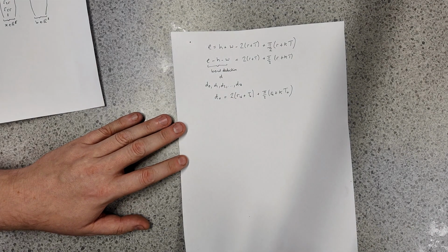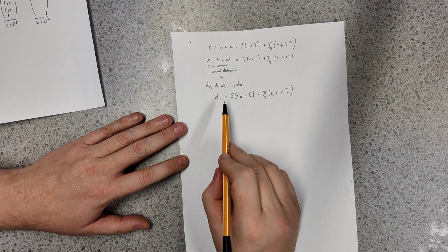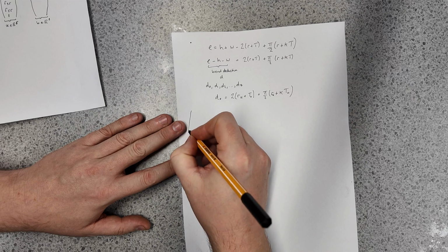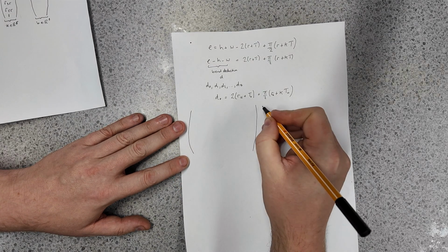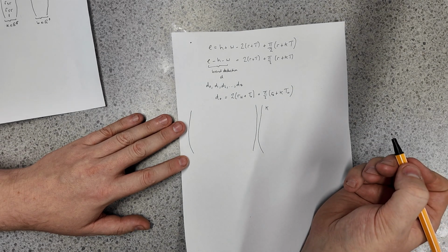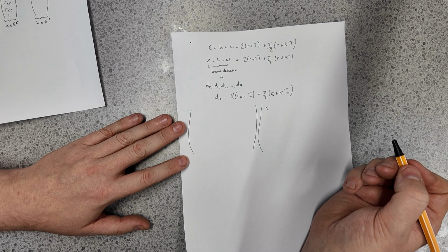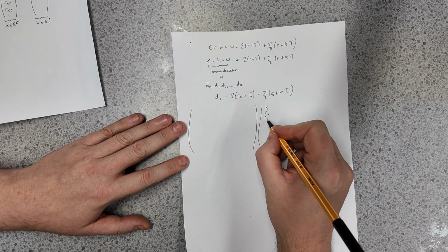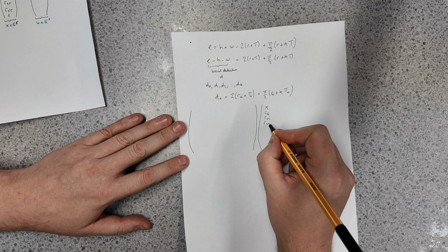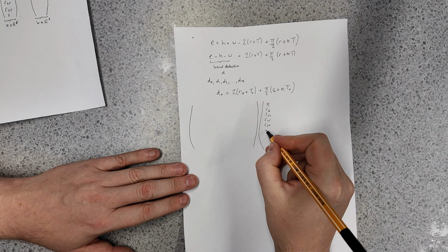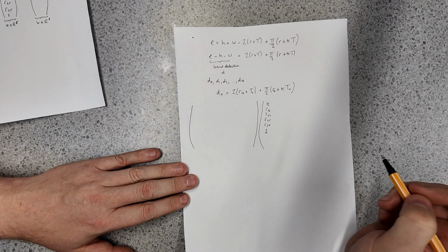So what we can do is write this in matrix form, and we can sweep D, T and R over the matrix. So let's write this down. We can write K, because we're going to assume that K is constant for all of the bends that we're doing, because it's all steel, hopefully from the same batch, although different thicknesses. And then we're going to write R16, then we've got the radius for the 22V, the 35V and the 50V, and for convenience we're going to write a 1 here, which I'll explain in a minute.